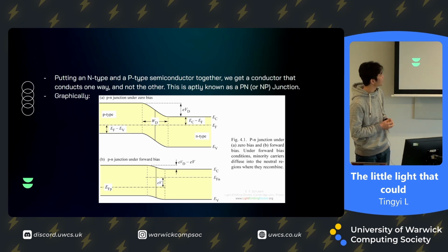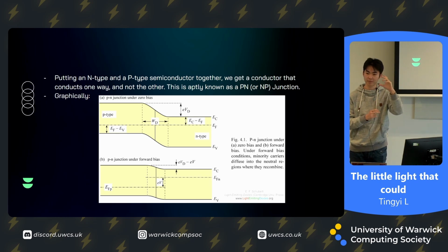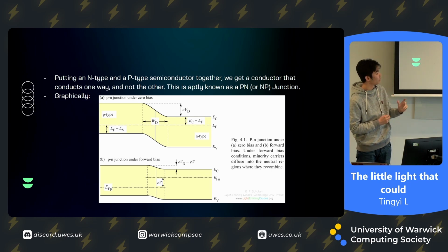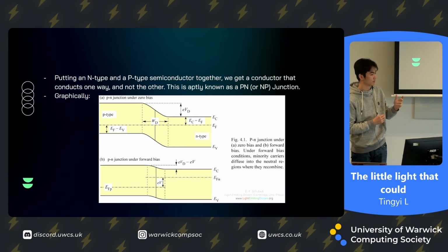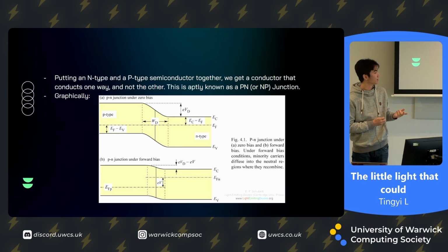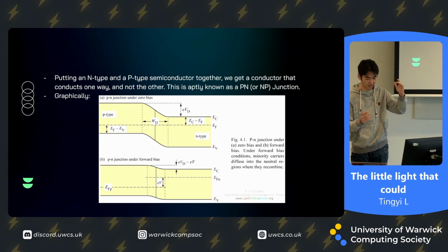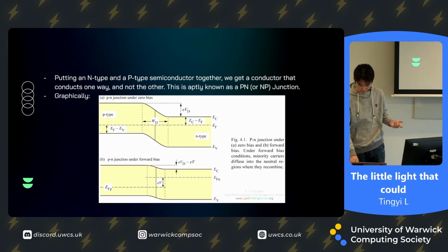In short though, how does this create light? When electrons flow, there is a band called a conduction band. When conduction band electrons fall down into electron holes in the P-type material, called the valence band, that fall in energy creates a photon because of wave-particle duality, E equals hf, whatever. Essentially, when you connect it the right way, conduction electrons fall down into valence electron holes, and that jump creates a band of wavelength of light.